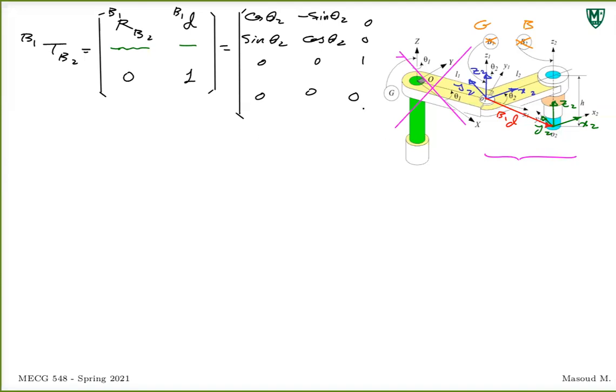Right? So once we're in the blue position, remember I was in the red position, I rotated theta 2 amount about z, this is the rotation matrix, so I got to blue, orientation is right. Now I can do the translation. Translation would be dB1.